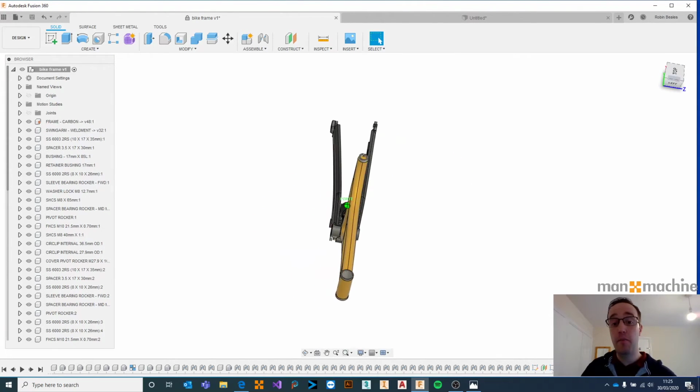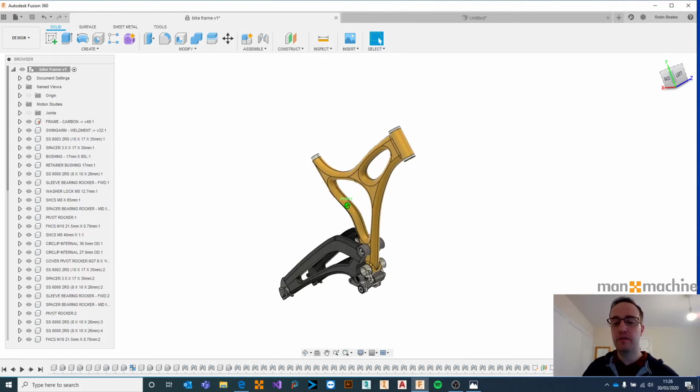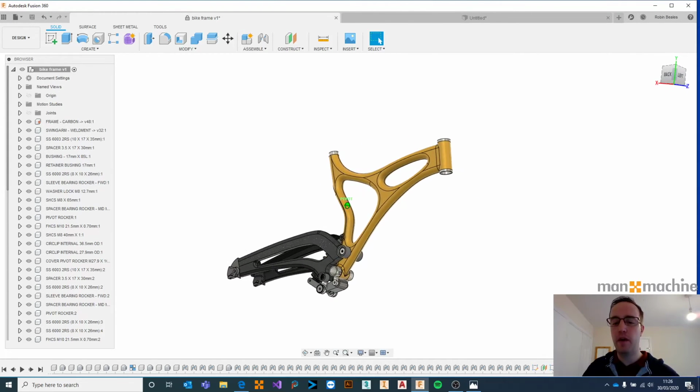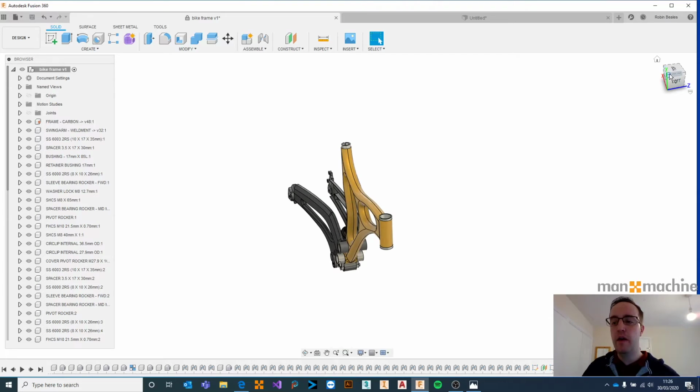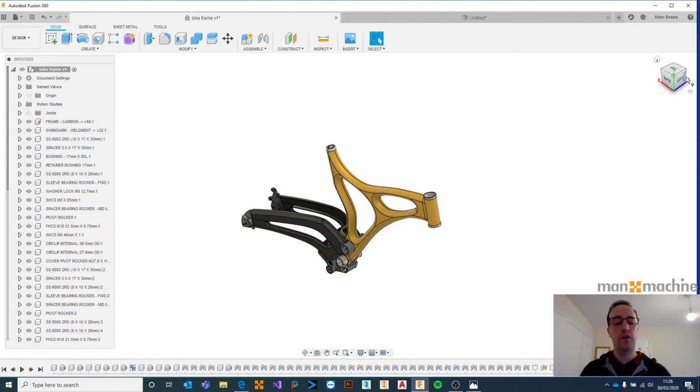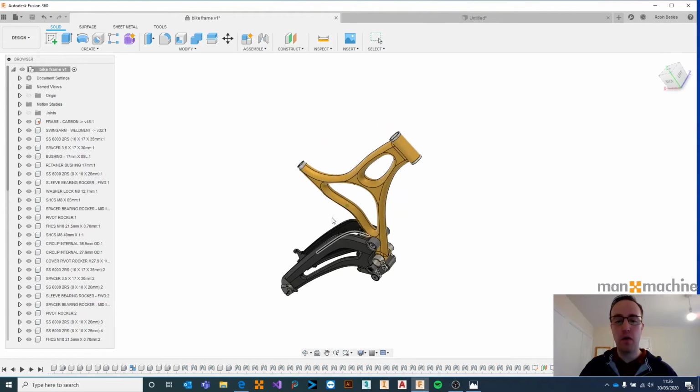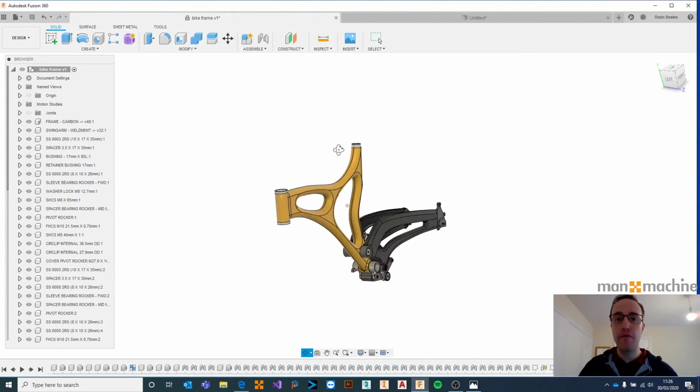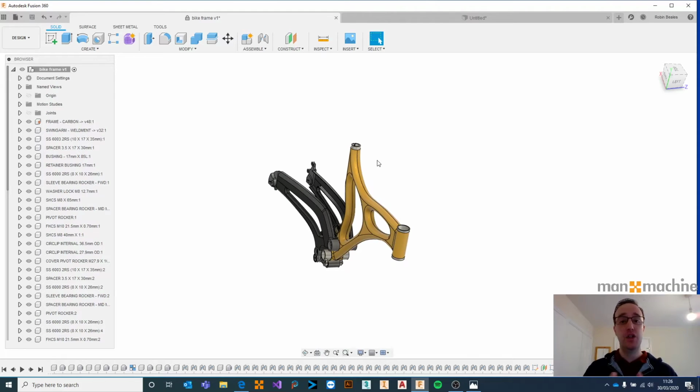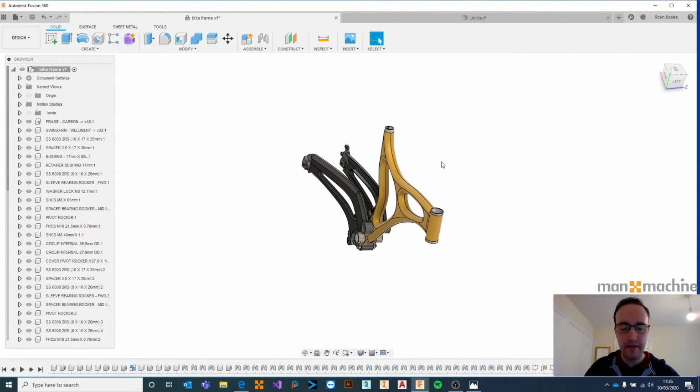Now, to me, that actually feels unnatural because it's not the way that I've been doing it for many, many years. So you really want to be getting used to that shift and middle mouse. It's much easier, and it means that you can do things with your mouse in and around the model rather than keep coming up and down and up and down. Over your life of using a design application, that's what you want to be doing: as little moving as possible, spending as much time in and around that model. But you have got the view cube there should you need it.